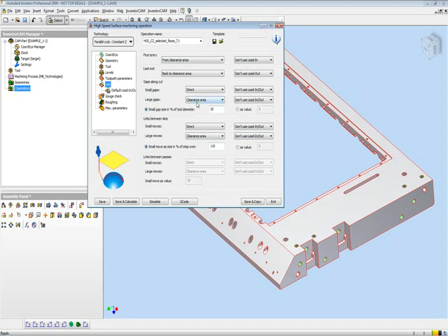If I have large gaps, as shown over here, I can simply say direct. What will actually happen is it'll go directly over the gap as shown in this picture over here from one area to the next. In addition, I also have link between slices. That means at the end, how do I want to go from one slice to the next? And if I have a large slice, I also want to do that directly.